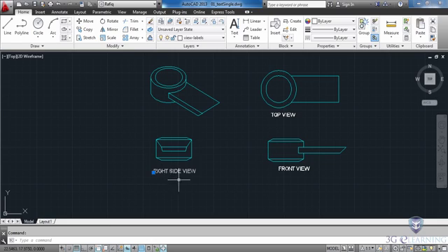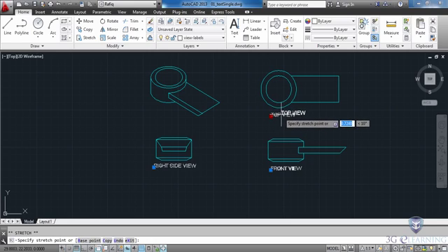One important thing to note, these text objects are just like any other entity in AutoCAD. We can move, rotate, or copy these objects. I'd like to move this label a little bit. I'll do that by clicking the grip, and I'll push this up and center it a little bit better on this view. As long as I'm at it, I'll click the front view and we will push it up a little bit farther. And I'll take the top view and I'll move this over to the right a little bit. When I'm finished, I'll press escape.